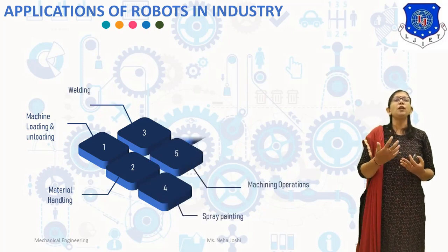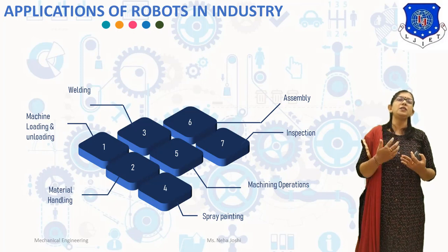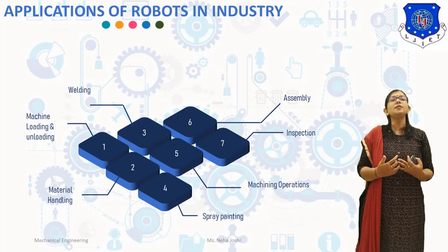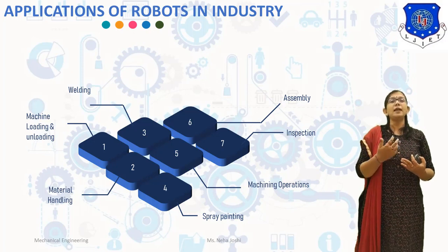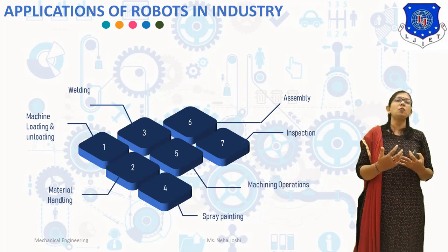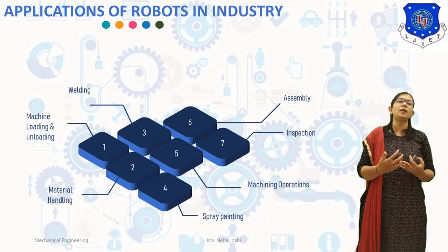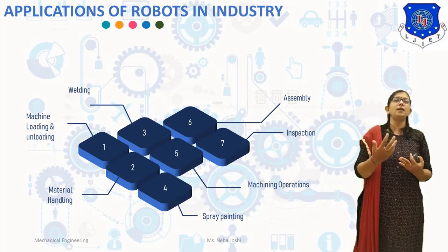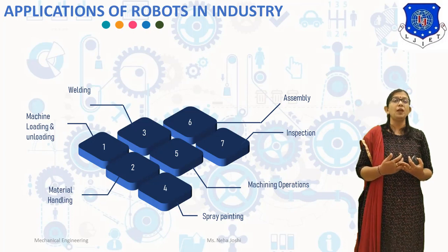Robots are used for loading and unloading of parts in CNC machining centers, flexible manufacturing system, die casting machines, punching press. The use of robots in such machines reduces the part handling time, thereby reducing the cycle time and improving the productivity. In machine loading and unloading, a robot should be able to orient the workpiece correctly so as to locate it accurately to machine after picking it from the bins or conveyor.